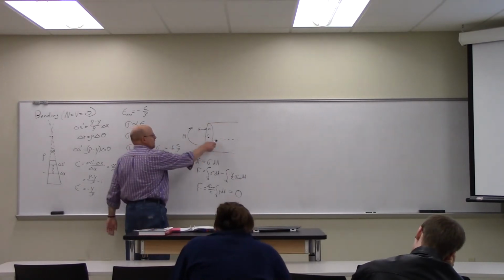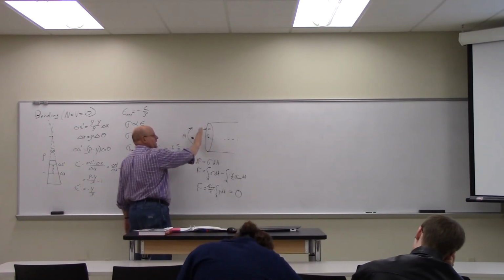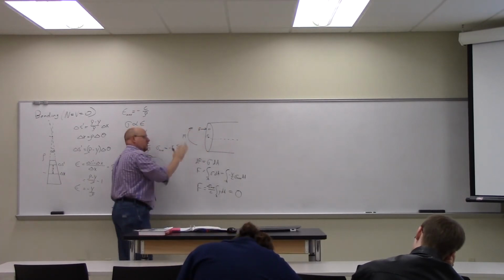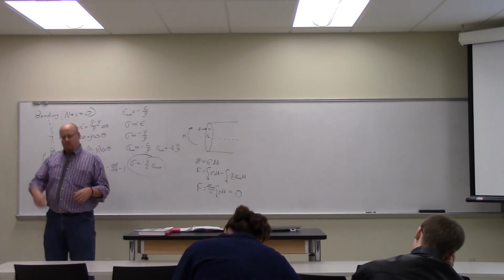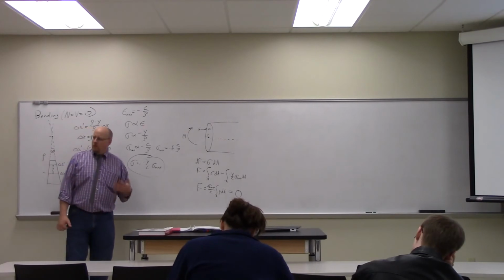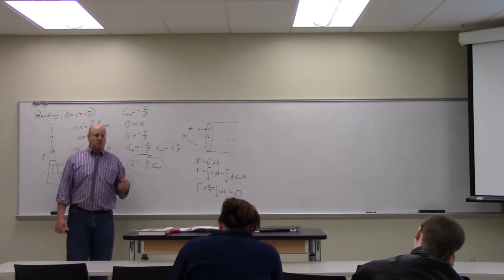Then we have to define the neutral axis as being the centroid of this plane, but the centroid in terms of the z direction is just the center because it's a symmetrical beam. Friday we'll talk about unsymmetrical beams, which seems like a weird word, but it is.